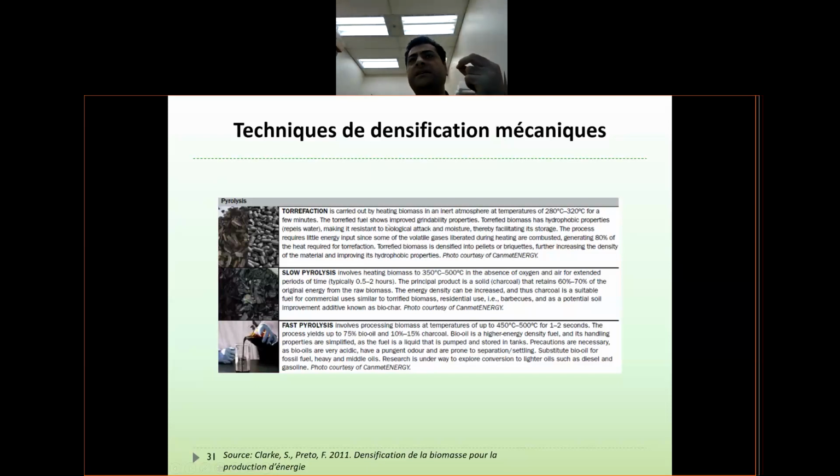The definition of particle density is based on the total volume of the particle, regardless of the empty spaces. We ignore them. So the mass per this total volume is called the grain or particle density.